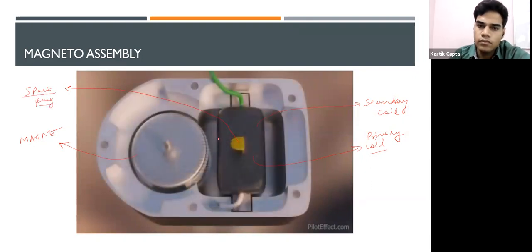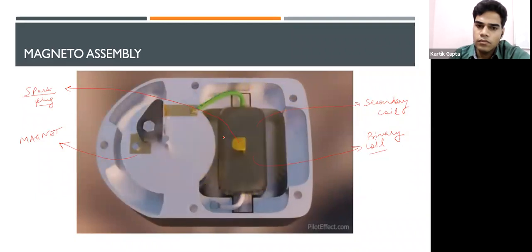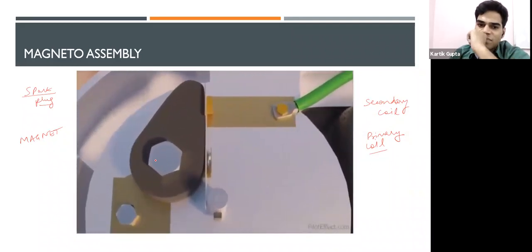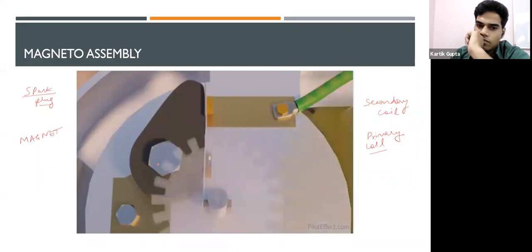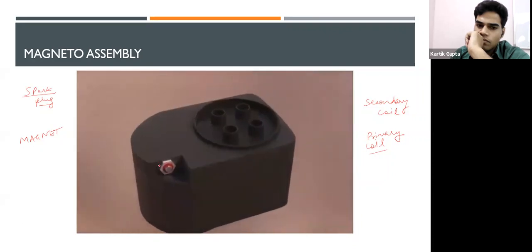Now let's cover a couple of select details before I wrap things up. First detail, the disconnecting of ground on the hot wire from the primary coil is accomplished through breaker points. The contacts are open, disconnecting the ground connection, which leads to the voltage spike in the coil assembly. And the last detail, there is more than one spark plug to consider. This is the distributor. As I was telling you, the distributor has the job of distributing the sparks according to the requirement of the spark plugs.